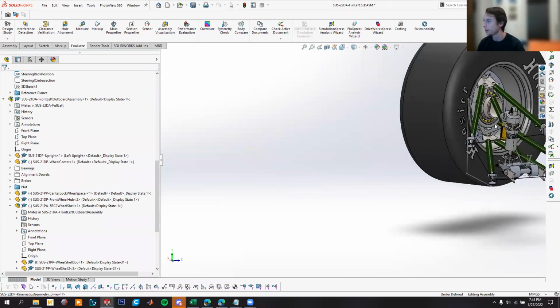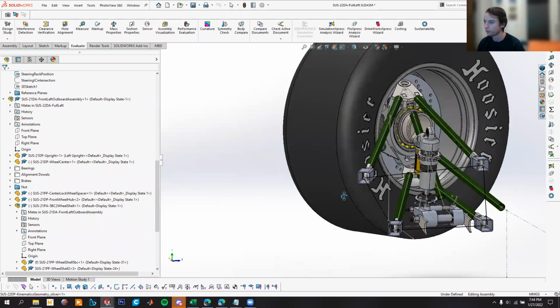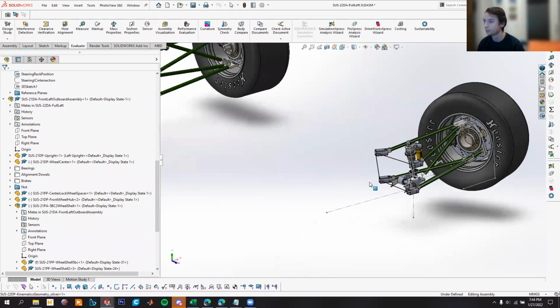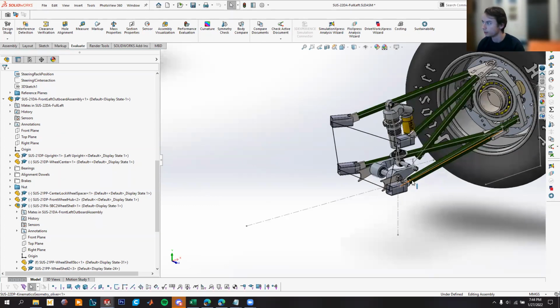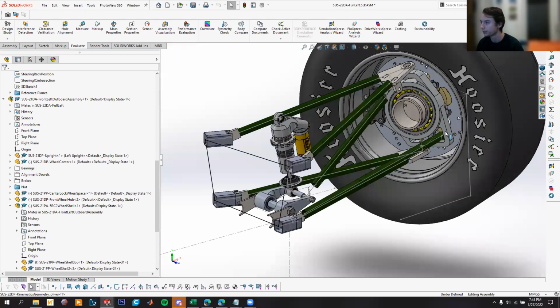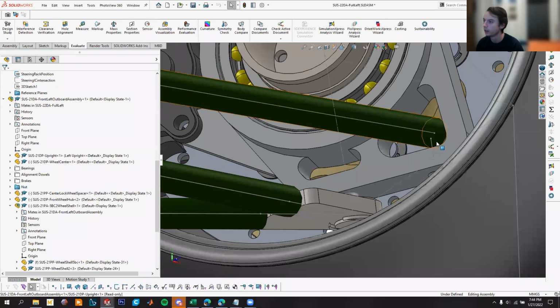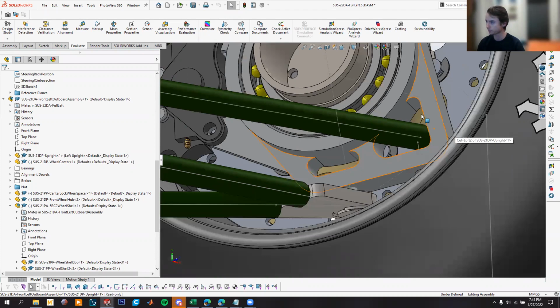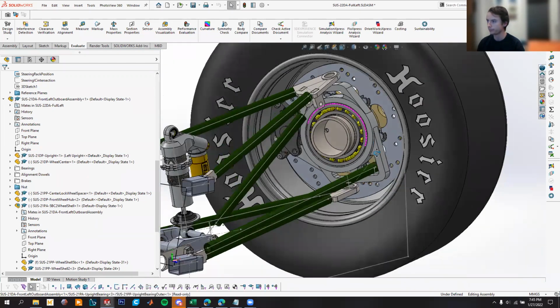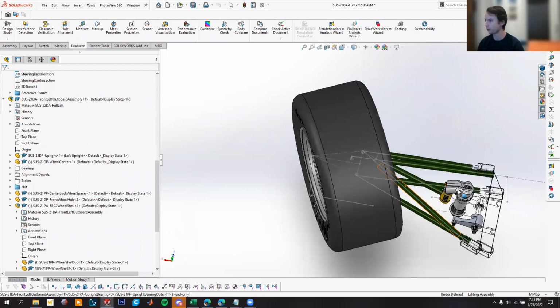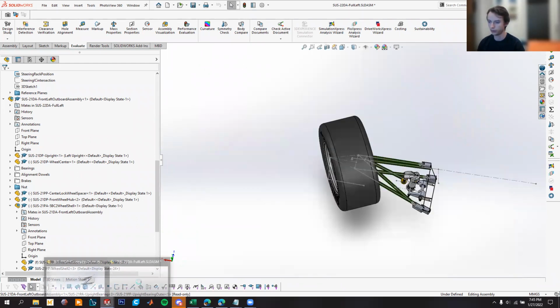And we can modify our amount of full steering on track by adding spacers and stoppers to our steering rack. There might be some interference here with the end of our steering link, but that's to be expected because the rod end isn't modeled. We're going to modify the upright in testing to see when it interferes. So that is okay. That is our full bump, full left turn.